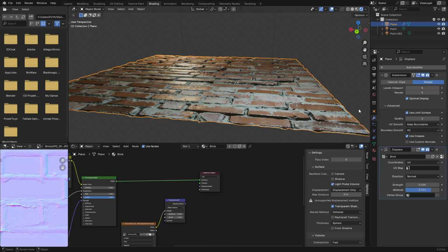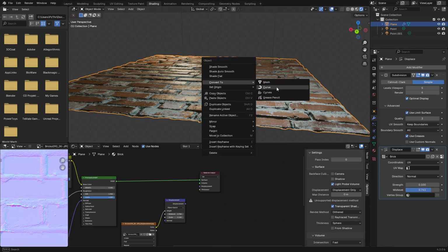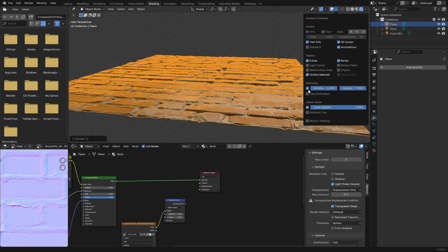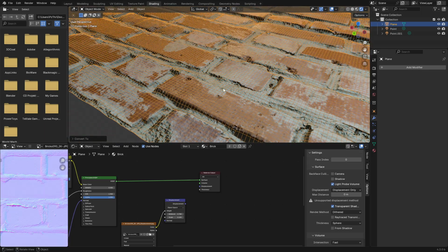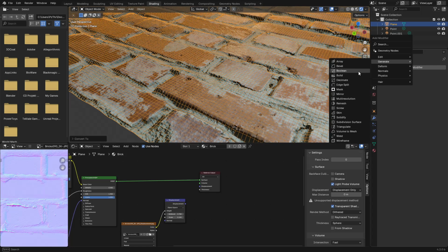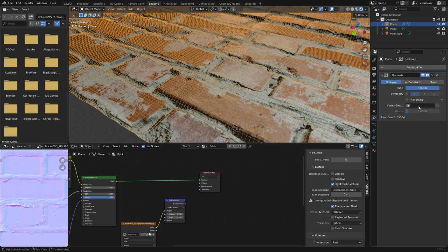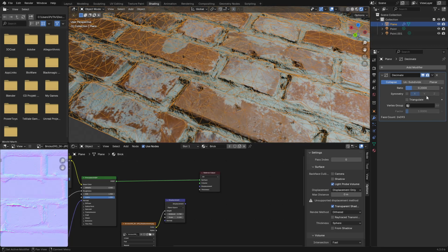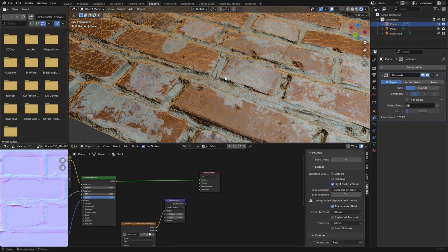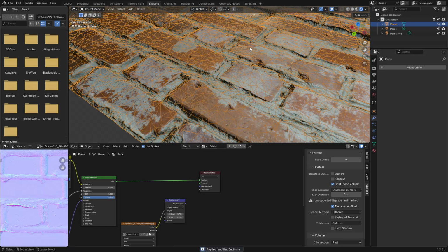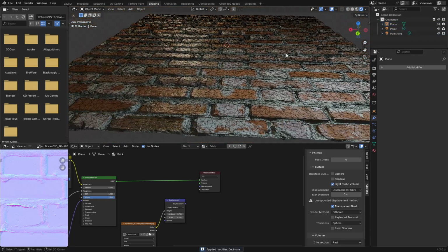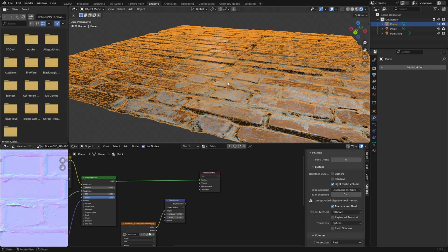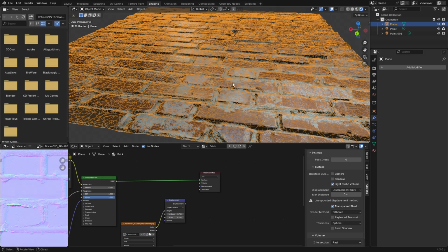Like with this setup anyways, you can always convert this to a mesh. If we look at the wireframe real quick, if we just do wireframes on, it's very dense. And if you want, you could try doing something later on like a decimate. So generate decimate modifier, maybe bring it down to like 0.2 and you'll get a lower triangle count here, but it's not going to be as demanding as having a higher triangle count basically. So even for nanite meshes, this still might be preferable in a lot of ways because it's lower triangle count overall and it tends to work out better for file sizes and whatnot, right?